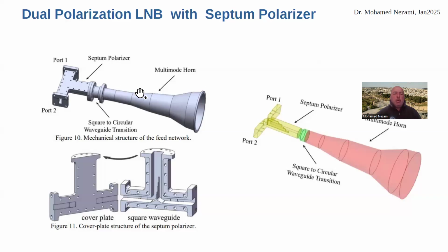The feed mechanism is responsible for collecting the signal with minimum loss. To preserve the sensitivity of the receiver, because such a low signal is coming from hundreds or thousands of miles away, we need minimal loss between the phase aperture of the horn antenna and the ports of the signals.